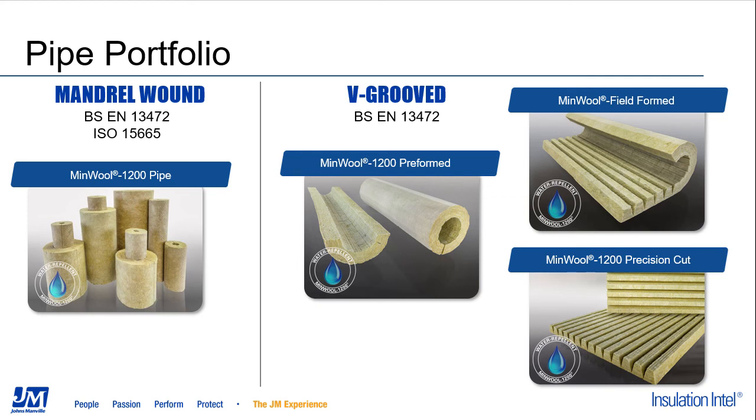And then 3 different formats of the V-grooved material, and this is basically a board format of mineral wool that has precision grooves cut in it such that when you curl it around the pipe, those grooves close completely and it actually looks and behaves exactly like a molded piece of mineral wool pipe insulation. The V-groove product's available in 3 formats, what we call preformed, so we pre-curl it for you and ship it either in a one piece or in a half shell set format.